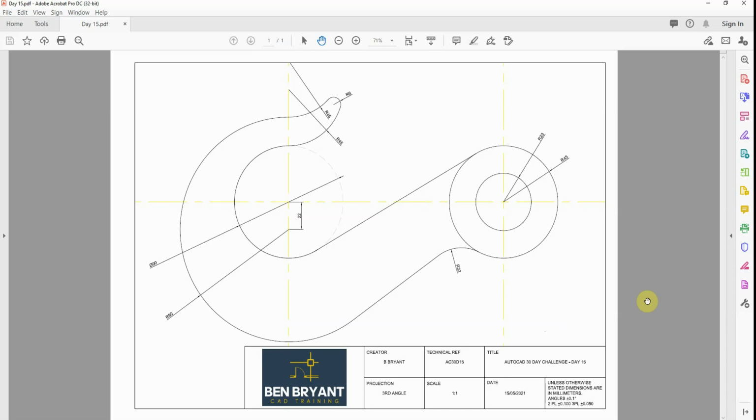Okay, evening everyone, this is the walkthrough for day 15, and today obviously we're trying to work on this little hook or mechanism. So what I'm going to do today is replicate the centre construction and start working in an orderly fashion, within the circles and plotting it around as per the set dimensions. As I mentioned this morning, this point here, centre point to centre point, is 178. Otherwise you have to do some maths and work out the triangulation between the 2 points.